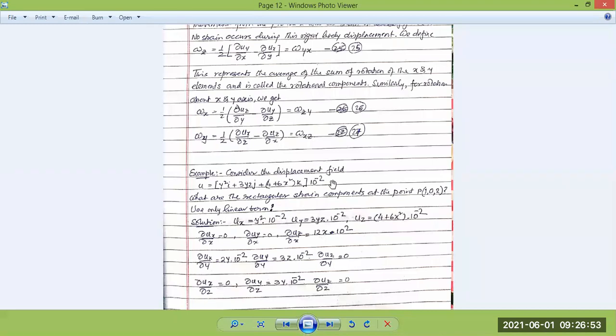Anywhere, if we know the initial point and the vector displacement field of a mass or unit, then we can calculate the displacement of any other point in the same mass of matter, using the displacement vector, displacement gradient as well as the initial coordinates.